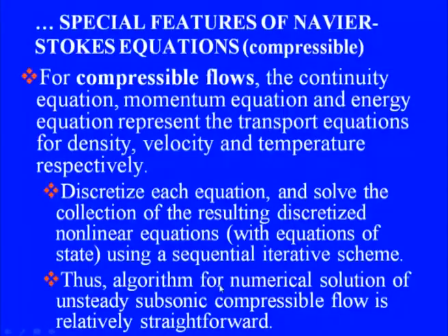In fact, if you are using an explicit solver, the solution becomes very simple. We do not have to use a sequential iteration scheme in that case. So, in algorithmic terms, the algorithm for numerical solution of unsteady compressible flows is relatively straightforward. Of course, there are issues which we will have to take care of when we go to hypersonic compressible flows. There would be formation of shock waves which have to be accounted for. So, the solution process would be a bit involved. We have to take extra care in that case.